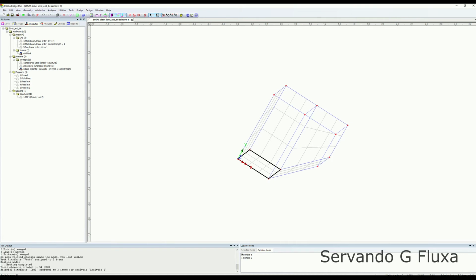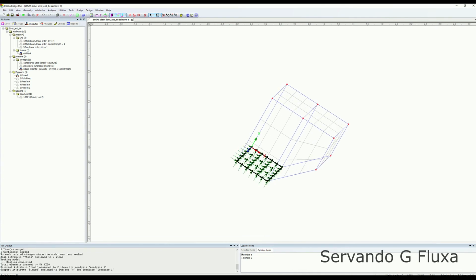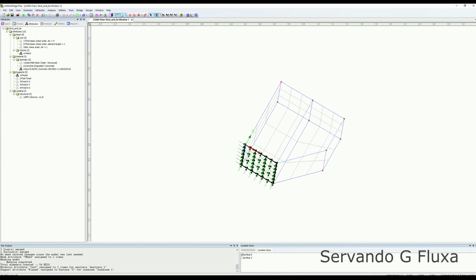There's here already pin, fully fixed, fixing, whatever. So I'm gonna drag the pin and assign them there. Assign to surfaces, yes, perfect. So those are my supports. So that represents that wherever I have a column basically here, this cannot move. Actually, they could be fixed, but well, as there are so many pin supports, it's like this fixed.